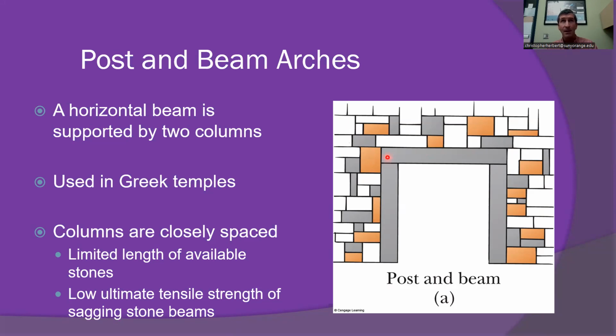And in fact, many of the structures would replace this overall top beam with wood, which is weaker than stone under compression, but actually because of the lignin and cellulose, it can have a higher tensile strength, especially for the same amount of mass. So the post and beam type construction was very, very limited, where you had to have a lot of supports very close to one another, or you couldn't have large openings.